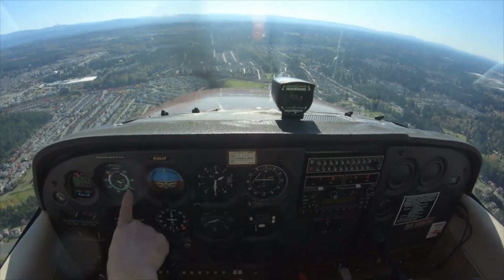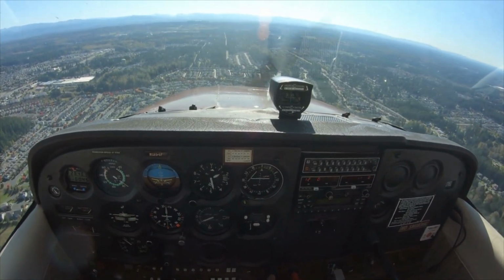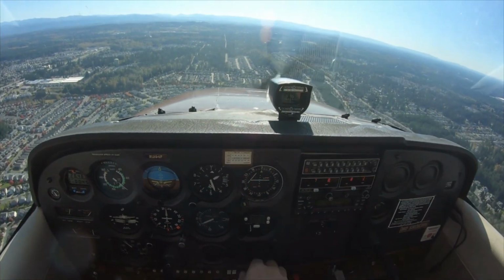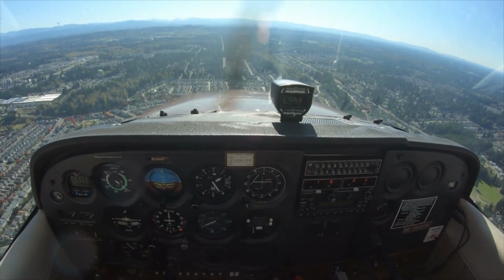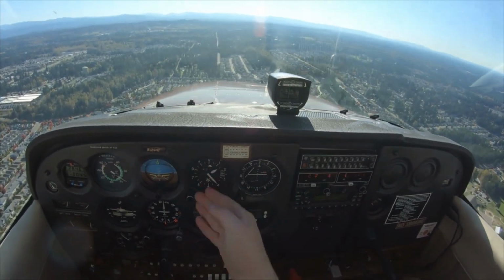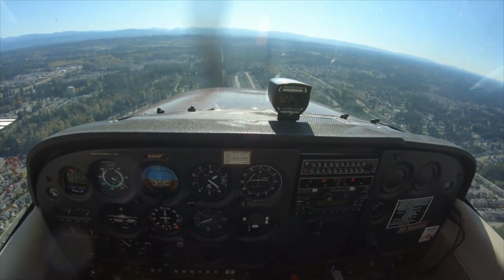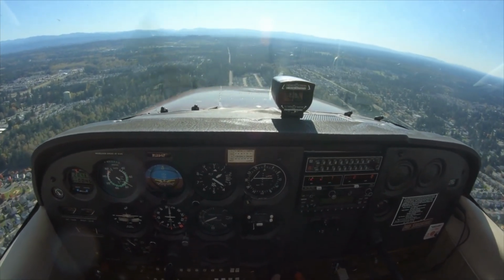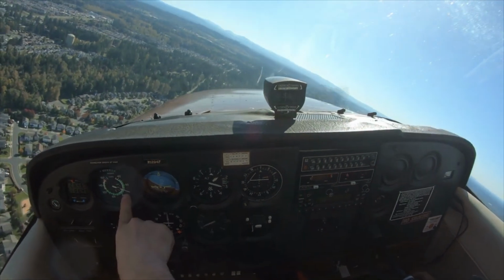Touchdown should occur at the minimum controllable airspeed with the airplane in approximately the pitch attitude that results in a power-off stall when the throttle is closed. Care should be exercised to avoid closing the throttle too rapidly, as closing the throttle may result in an immediate increase in the rate of descent and a hard landing. Note that a small amount of power provides more airflow over the elevator, giving it more authority at low airspeeds to enable the pilot to flare.